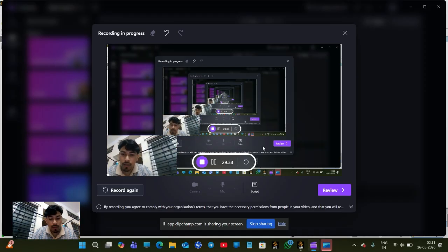Simulate natural convection in a square cavity with the top wall adiabatic, the vertical walls isothermal, and a bottom wall where the heat flux is given as q = Q0 sin(πx/L), with Q0 as a reference heat flux. We need to show the velocity vectors and temperature contours. And now I want to proceed with my solution.